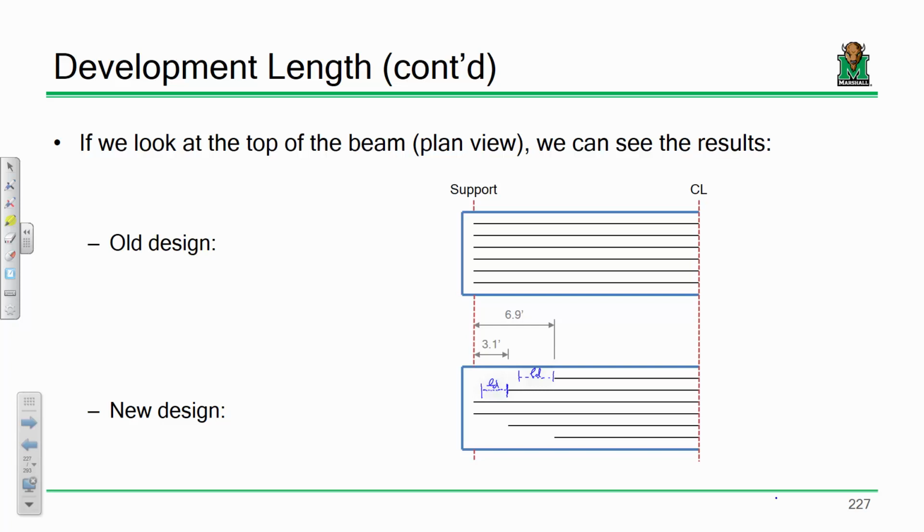The big point that I'd like to get across though when it comes to this development length, was that equation really that hard? Like really? It's really not. You just have to look up the factors and you plug and chug. A lot of what we're talking about with bundling and so on and so forth is the same story. We're not going to cover everything in this class, so you might get into a design office and somebody might ask you, well, what's that? It's not the development length, but it's going to be a very similar plug and chug expression. So just something to keep in mind.